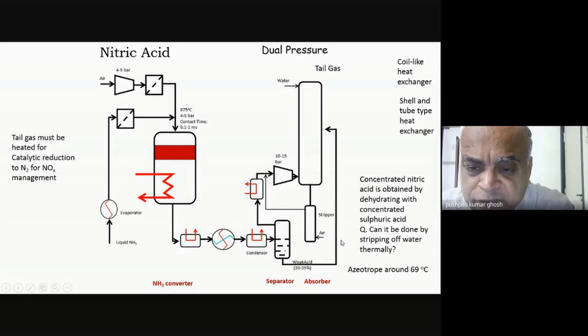And what you do is that you purge it with air so that it strips off any dissolved gases which might be present in the final nitric acid. You take it out, like NO, etc. Some more air is being fed along with the NO that is being released. The air also is beneficial because in the process of oxidation in all these points, naturally the oxygen in the air is getting depleted.